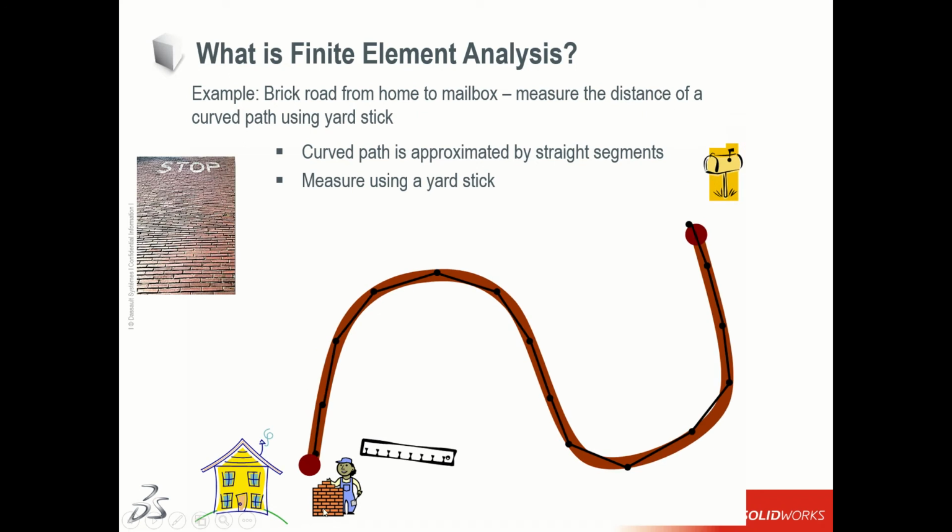First you will put one roller here and measure the first distance. Then at the end of the second point you mark that end point, put the roller again, and calculate the next one.